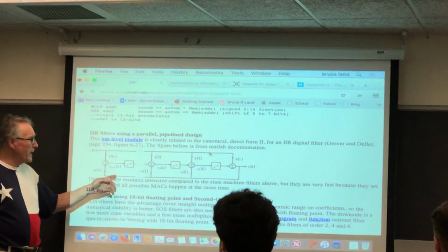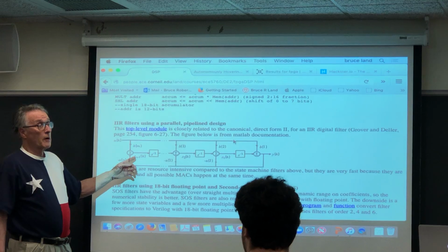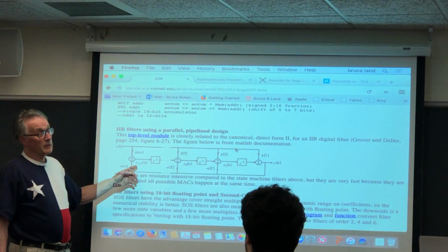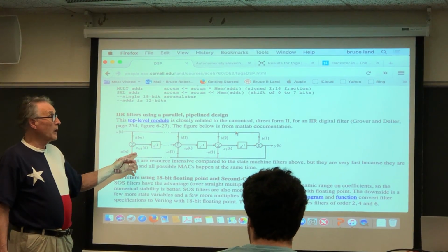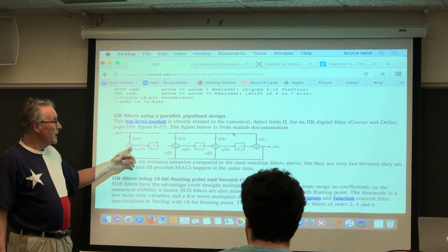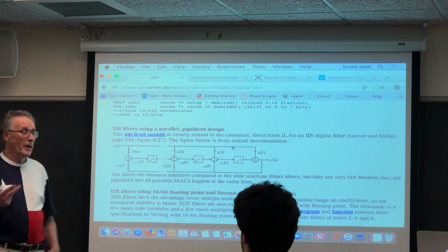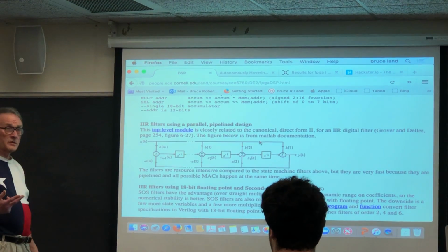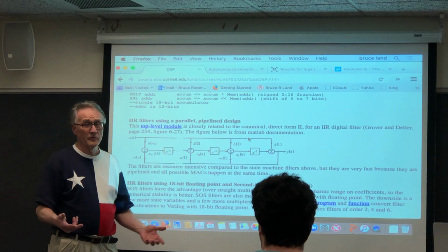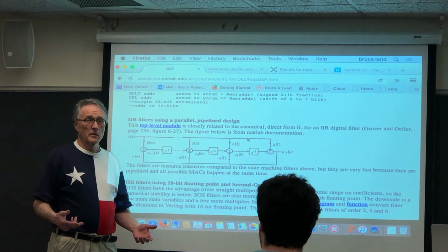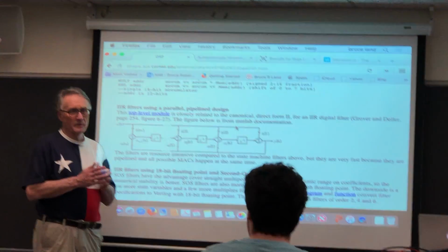So you could do about an 80, well, it depends on how many bits. If you do 18-bit, you could do 180 tap finite impulse response filter, or 280 tap FIRs, completely in parallel at bus rate, so 150 or 200 megahertz, if you wanted to do some sort of baseband processing of some fast signal.